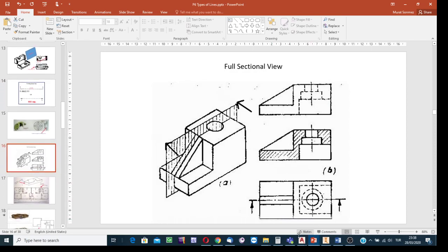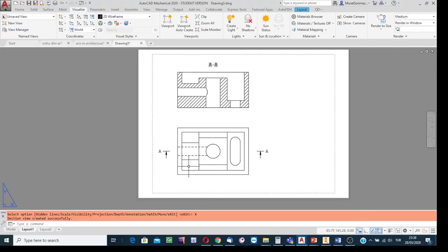Sectional view AA. Yes, in this example in AutoCAD, you see cutting plane AA. AutoCAD put the identification letters, and in the vicinity of the corresponding view we have this phrase AA. But the good practice is to write the preceding word section. Okay, later I'm going to educate you on the text facility of the software. Using the text tool you can write the preceding word. But here in this video record, I aim to demonstrate how a sectional view is created in AutoCAD.